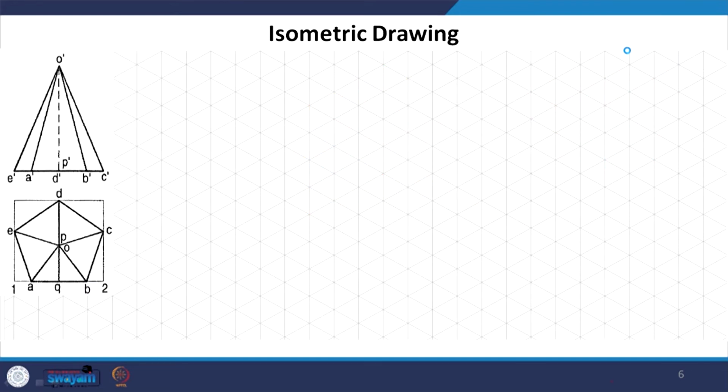Now, this is again this example where I have a pentagonal pyramid, again a straight pyramid, the same steps, the same process to be followed. So, what do we do first? We enclose this pentagon in a rectangle, a reference rectangle, and we arrive at these 5 points, and we also arrive at this point beneath the apex, okay.